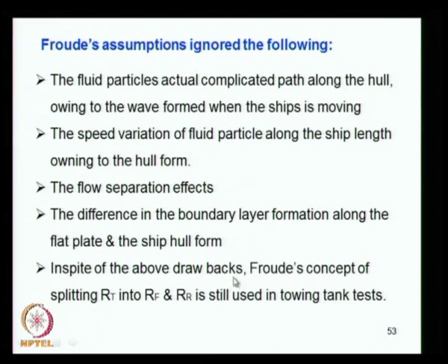The difference in the boundary layer formation along the flat plate and the ship has been ignored. We have highlighted many drawbacks in the assumption of Froude, where the split of total resistance into residuary and frictional resistance has been done.